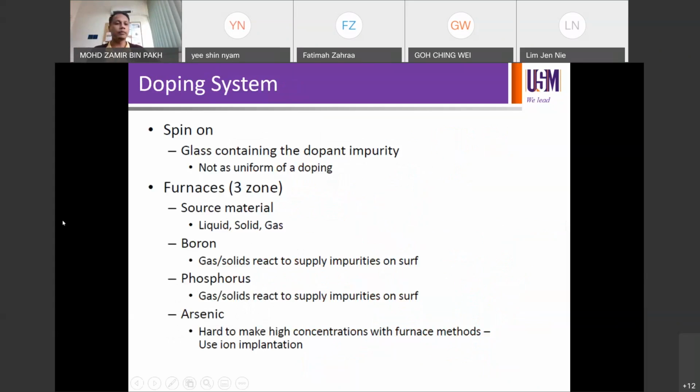All right, doping systems, we've discussed this one before. You can also watch this on YouTube. The doping process can be carried out by various techniques. The one you can watch on YouTube is by POCl3, phosphorus oxychloride, where we bubble the POCl3 precursor and use nitrogen gas to send the vapor into the furnace, into the boat, into the quartz, triple stack, industrial scale, and then start the diffusion process at high temperature, in the region of 900 to 1000, depending on the process requirement.